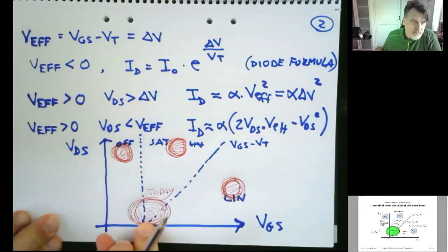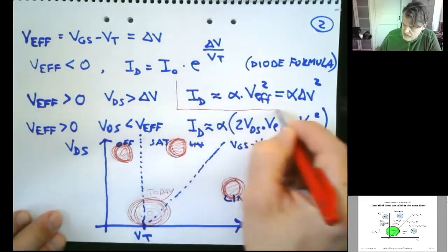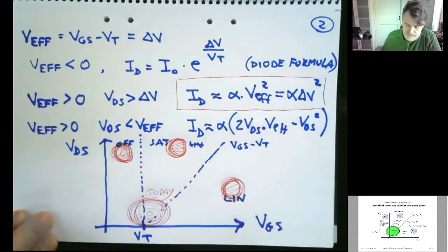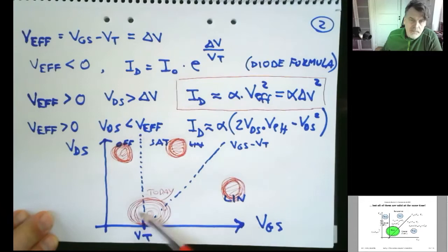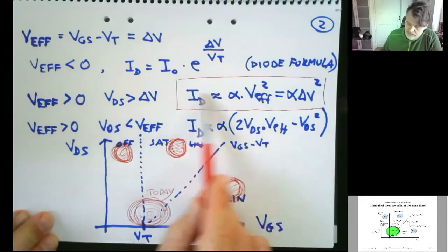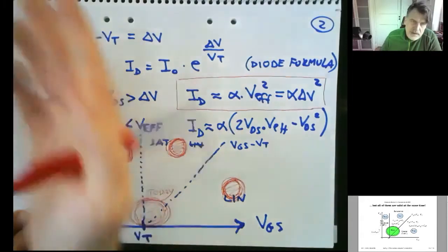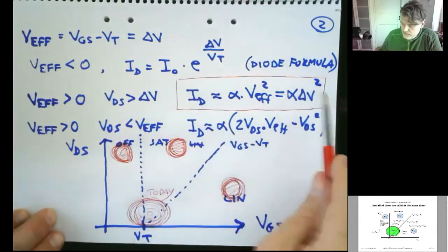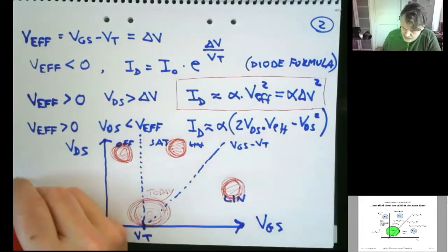So the solution to that, once again, is to become the lazy engineer and just pick one. So we pick the saturation region because it has quite nice formulas. And it gives you guidelines. These hand calculations will by design be incorrect due to this argument, but from this you will be able to derive certain directions. You might think, okay, I want to increase a parameter to increase the gain, or I want to do whatever I want to do. And then you have to go to the simulator as soon as possible.